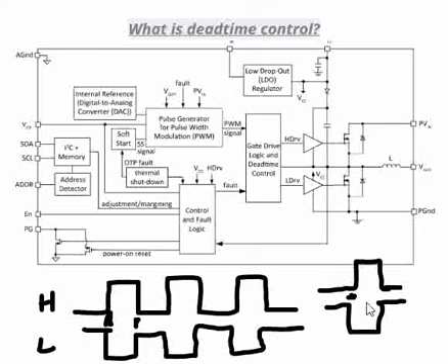This gap, the time difference, should be maintained between turning on and off of the high side and low side MOSFET. That's what this dead time control is going to ensure, where you will not have an overlap of turning on both the devices at the same time, ensuring there is no direct shot from power to ground, or the shoot through condition which we were talking about.